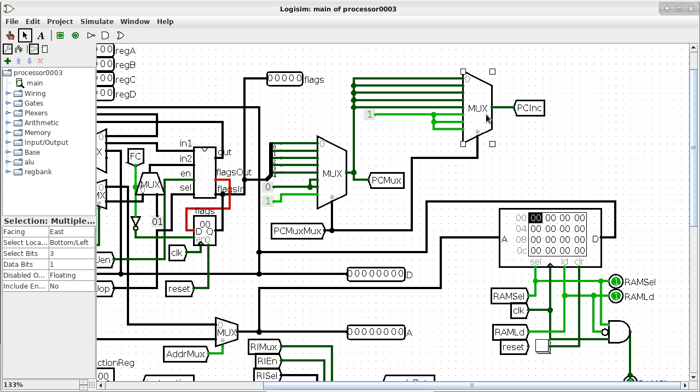If you have watched that show, you have seen the tracks switching, right? That's basically what it is. It's basically a switch. In the case of a MUX or multiplexer, it has multiple input pins and one single output pin, and then there's a selection to specify which one of the inputs connects to the output. At any time, only up to one input can connect to the output in a multiplexer.